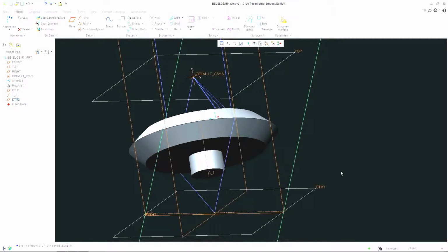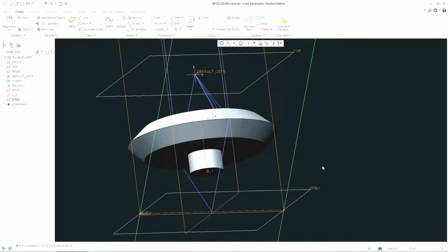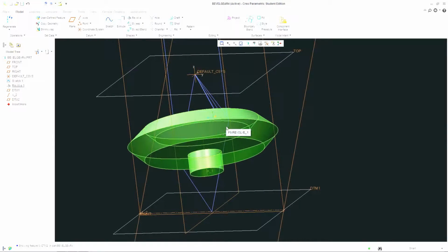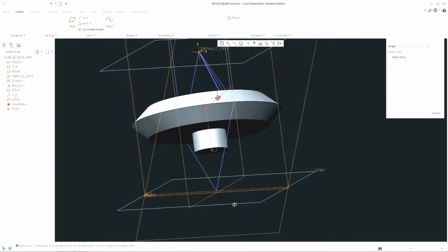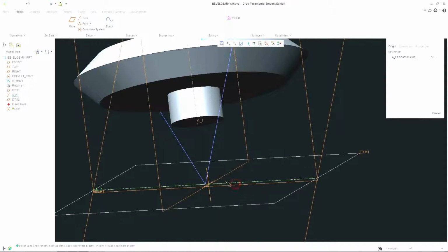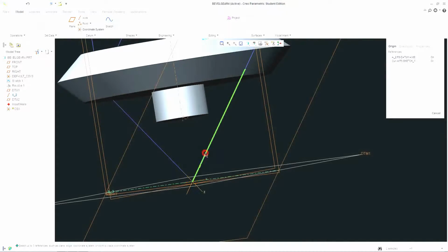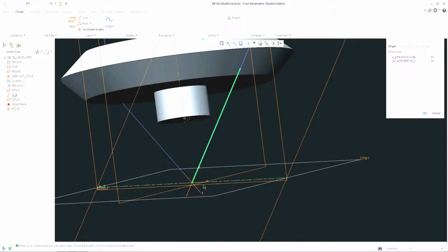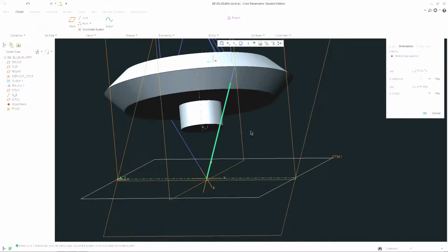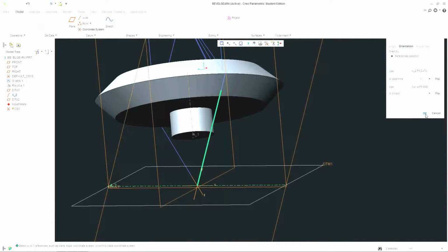the teeth. Alright, so we're gonna draw an involute curve now. For the involute curve, we gotta specify a coordinate point. So we're gonna use these coordinate points here. Click on that, hold control and click this line and this diagonal line. Hold control to select both of them. Just be aware where the X and Y is. Sometimes we need to flip that around. We can go here, we can flip the X or Y around, and that will let us control where the involute curve can be positioned.